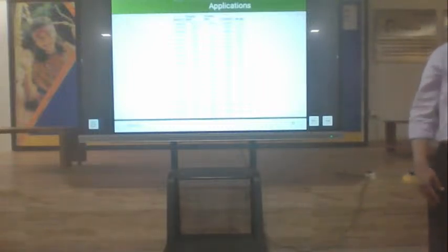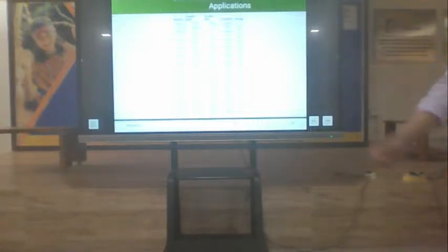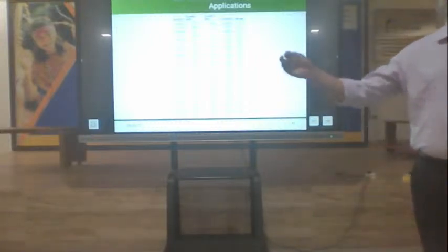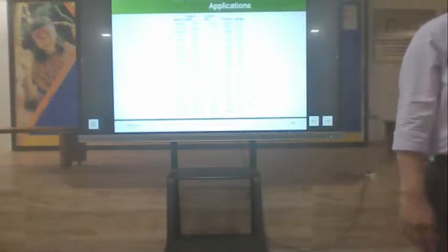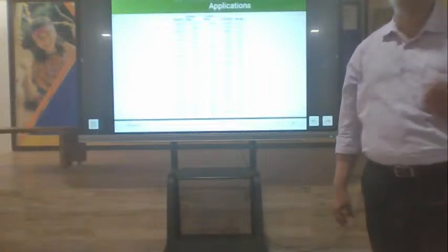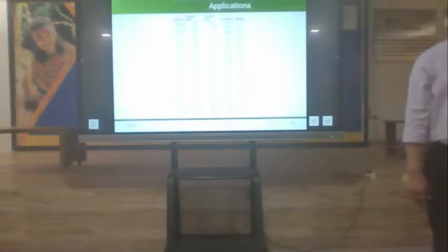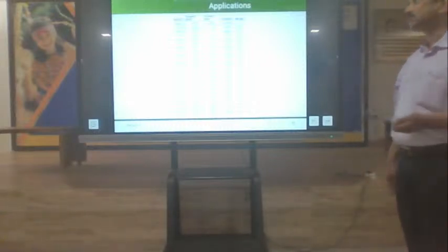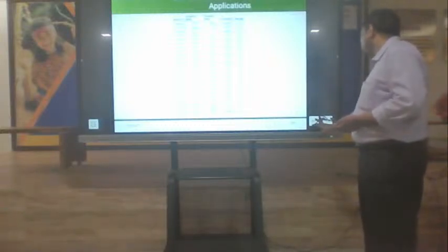The last mile is around 3 volts or something. 230 volts is getting converted in a laptop into 3-4 variants: from 230 you land up with 1.6, from 230 to 3.3, from 230 to 5, from 230 to 12. There are so many conversions, and each of them is going to waste 20% of the energy. If we can avoid those conversions, we can make a product which is efficient. That's what this is.